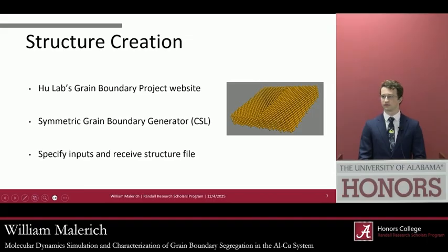What type of analysis do you plan to perform on the simulation results using C++? Yeah, so once we have results with C++, we'd like to do simulation to determine the free energy around the grain boundary, the amount of disorder, and the free volume, which is sort of how much open space there is, because those are very important parameters that determine segregation as well as the strength of the material.